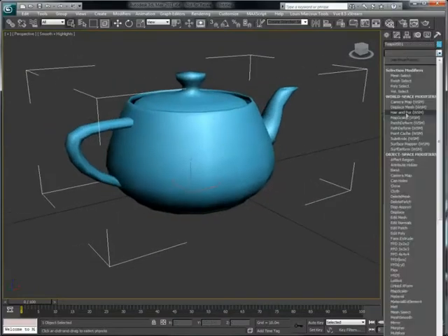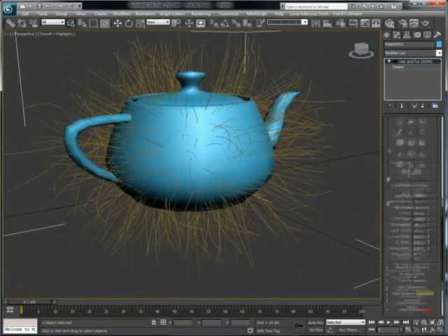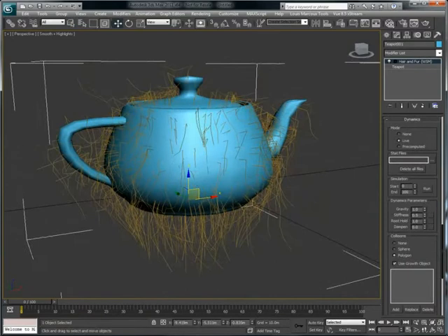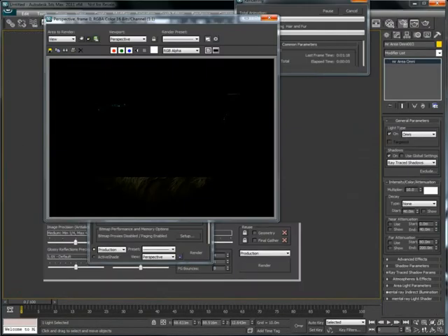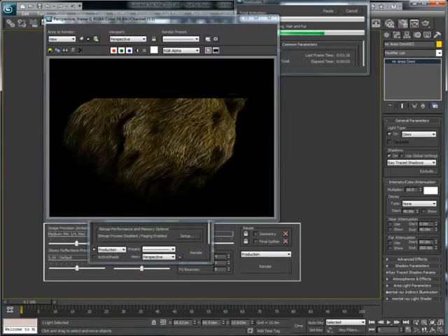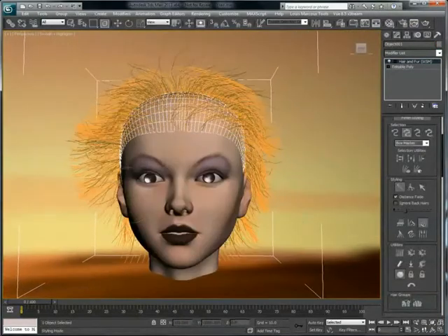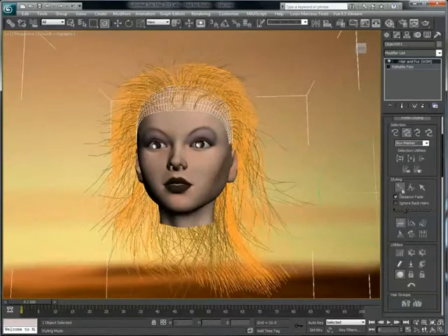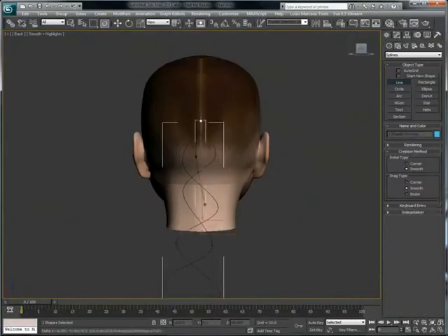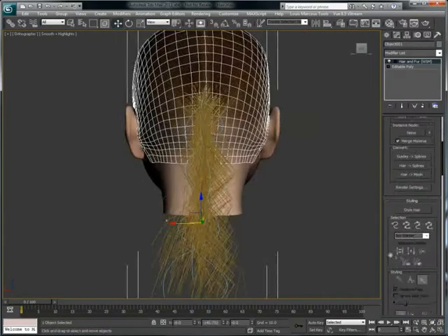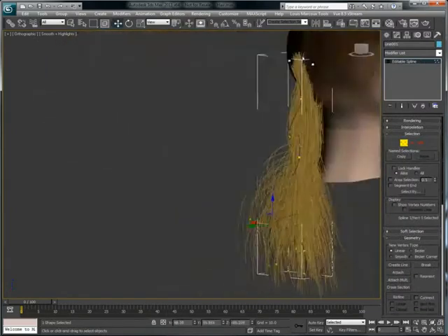For visual effects tools, let's start with the hair modifier, which is based on Joe Alter's Shave and a Haircut. The modifier can be added on any object to turn them or part of them into hair emitters. Styling tools help to shape up the hair, and extra parameters can define their stiffness, frizz, and kink. Hairs can also be modeled and animated from splines, which is great for long hairs and French braids.